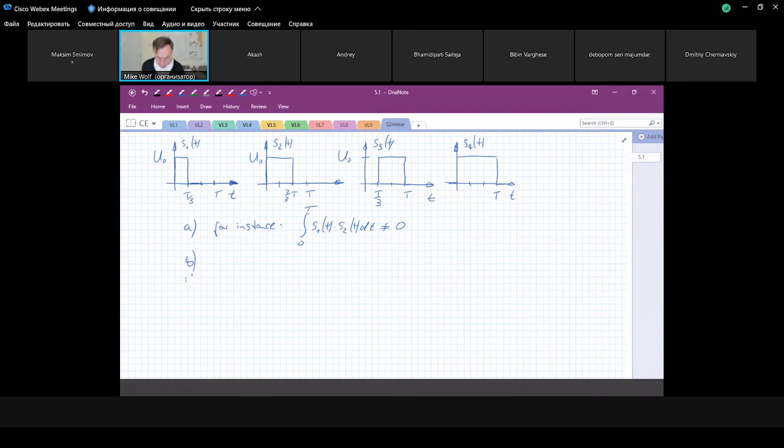You simply say, okay, I start with a basis function which has the same shape as the first signal. So we basically say S1 of t, so this is the first step. Step 1. We simply say the first signal should be represented just by one basis function, psi1 of t, with the corresponding weighting.